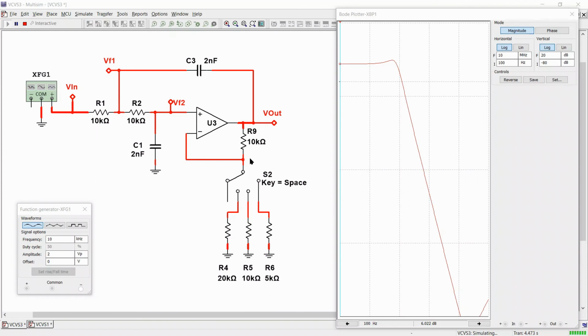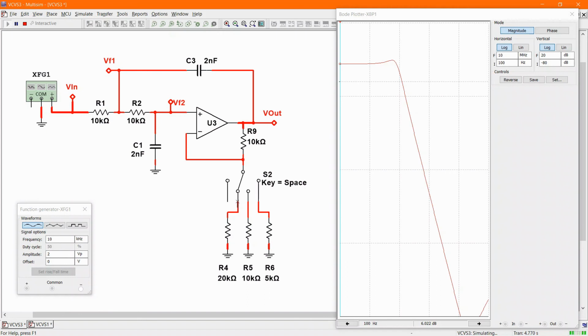Note that the concept there is that I'm making the output bigger and adding it to the input. And there's another way to make the output bigger, and that's to turn this op-amp into a non-inverting op-amp with gain. So here I've done that. I've added a couple of gain resistors here. If I'm in this position, then this goes straight back to there, and the gain is 1. It's a voltage follower. If I go to this position here, it's now a gain of 1.5. This is 2, and this is 3.